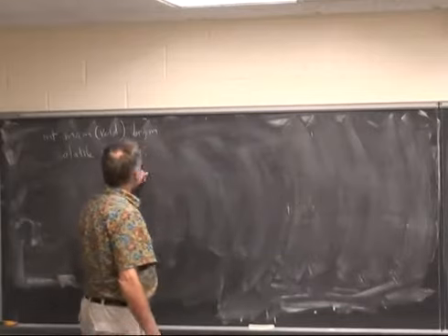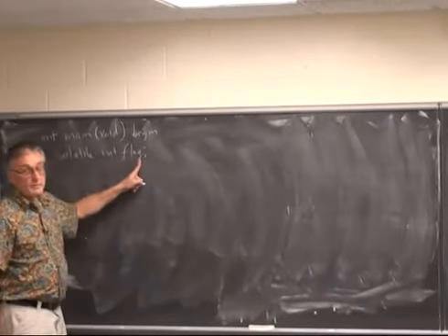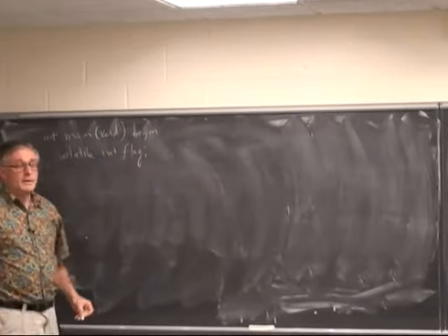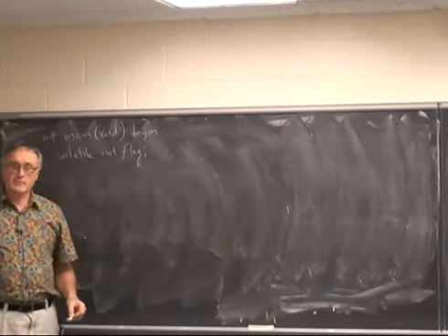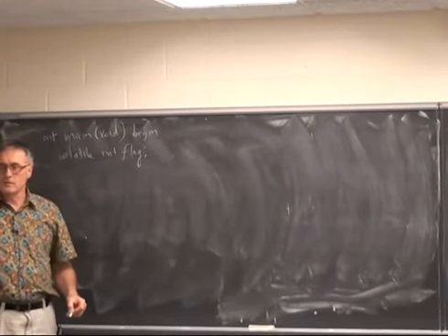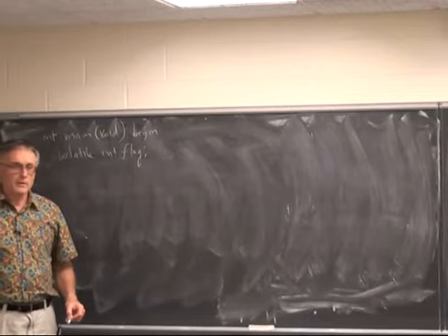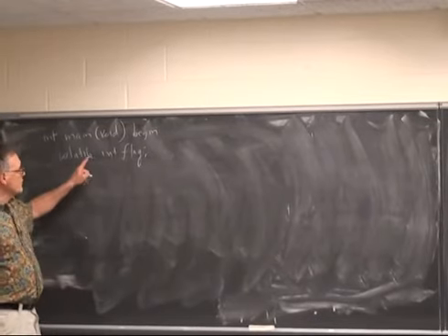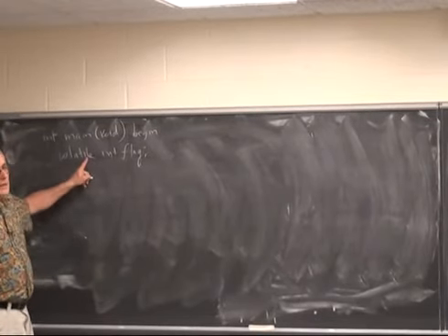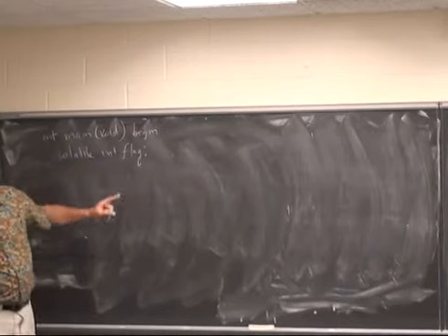Flag is never going to be modified in main, only read. The optimizer will look at that and say, value is always 0, don't need that variable, unless you make it volatile, which signals to the compiler that some other process can asynchronously modify this variable.